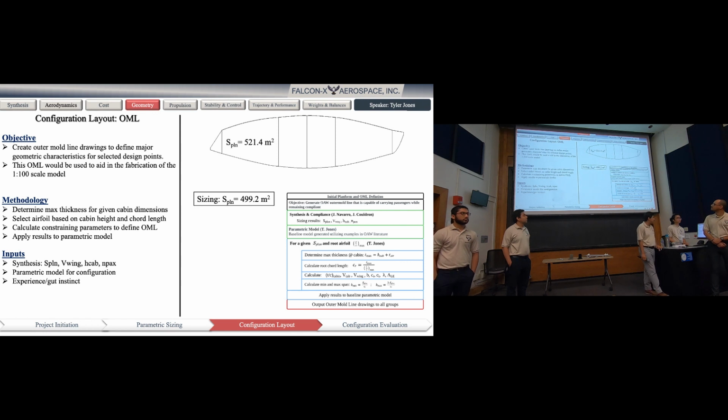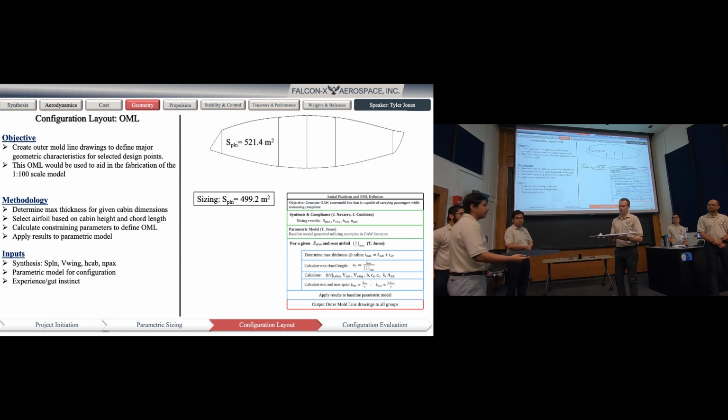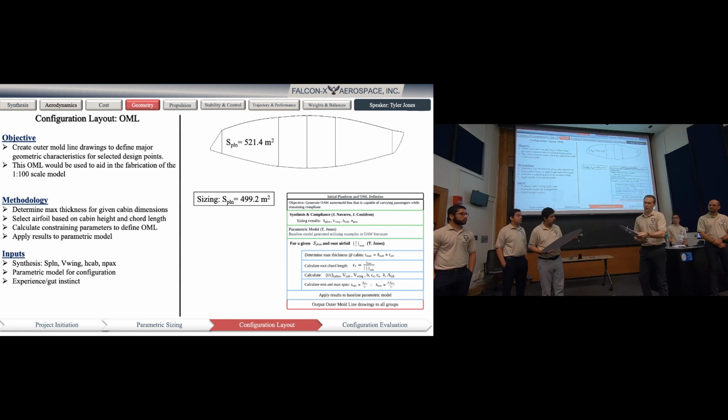Okay, so the outer mold line layout is the first real stage of the layout that begins to look like an actual flight vehicle. The thing about it that's challenging is as this configuration changes its orientation and flow, the performance of each part of the vehicle essentially changes. Here, unslewed, or at a slight slew, it's basically just a wing. Now there's no fuselage or anything else, but once it's in supersonic flight, angled at about 70 degrees, this wingtip becomes effectively the forebody of the vehicle.